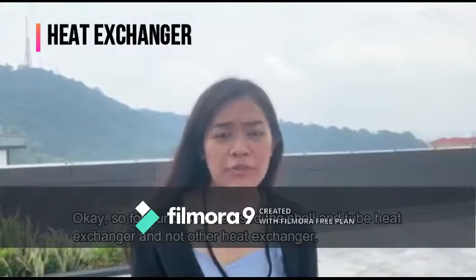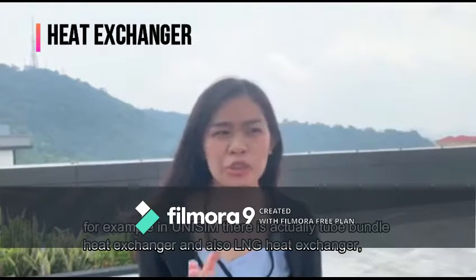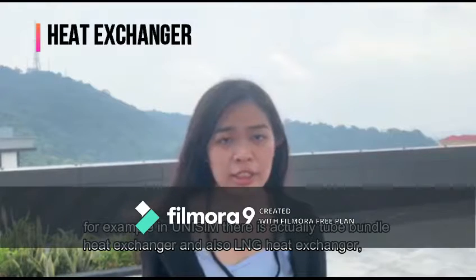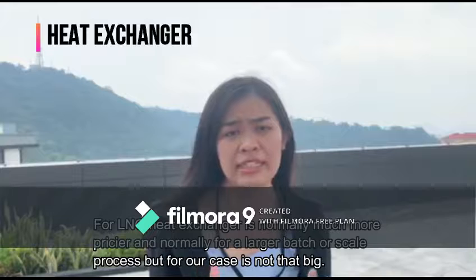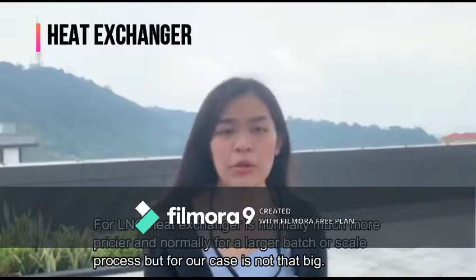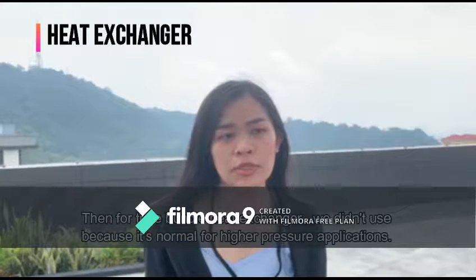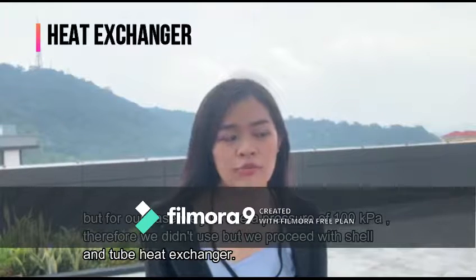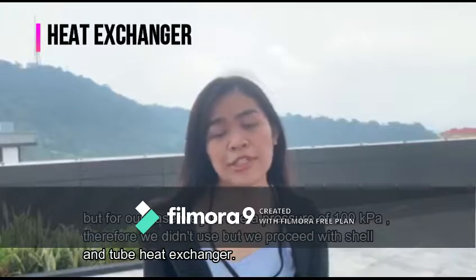For our case, we use the shell and tube heat exchanger and not other heat exchangers. For example, in UniSim, there's actually a tube bundle heat exchanger and also an LNG heat exchanger. The LNG heat exchanger is normally much pricier and it's normally for a larger scale process, but our case is not that big. Then for the tube bundle heat exchanger, we didn't use it because it's normally for higher pressure applications. But for our case, we just use a pressure of 100 kPa, therefore we didn't use it, but we proceed with the shell and tube heat exchanger.